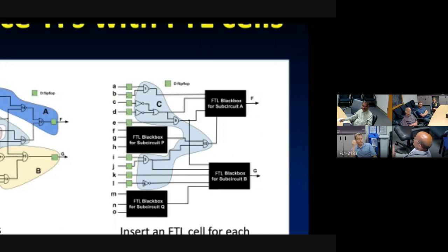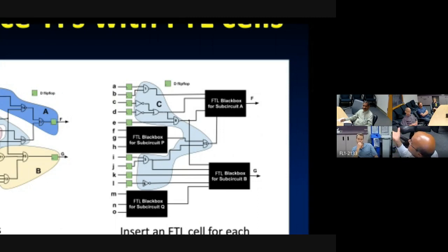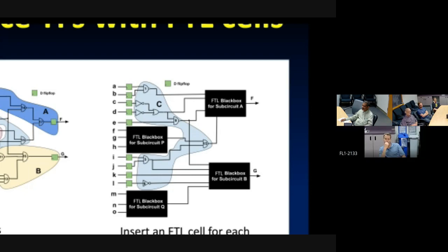You have this kill switch, which basically erases all the VTs of all my flash transistors. This chip is then just a piece of silicon and no more. It's completely inert, and that's something they like a lot. You can have a supercapacitor on the chip, which when it detects some event like this, goes and programs everything to a blank state. So that's kind of cool. And the good thing is when I get this thing back, I can reprogram it and it's functioning.